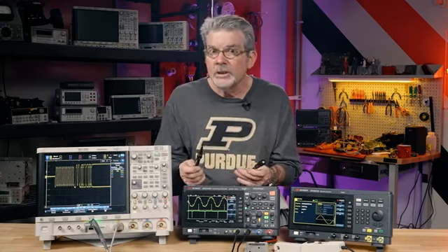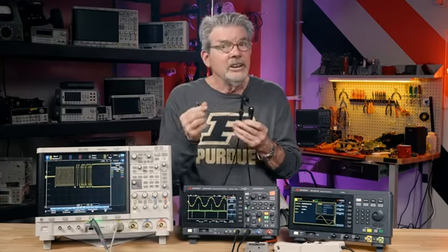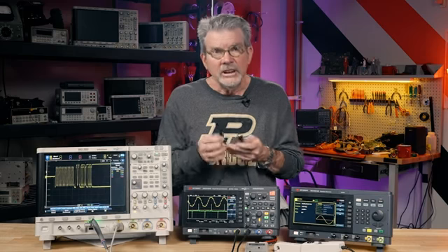Passive probes can only measure voltage. They can't directly measure current. Passive probes can only make measurements relative to ground. They can't directly measure differential voltages. And the standard 10-to-1 passive probes have limited voltage range. They can't measure thousands of volts. You'd blow one of these things up if you connected it to very high voltage. Let's now look at some of our alternatives for these cases.